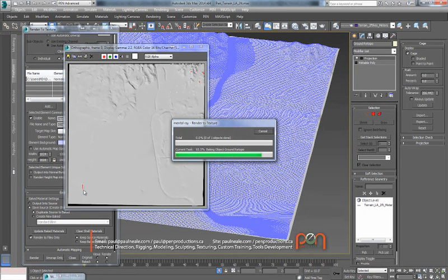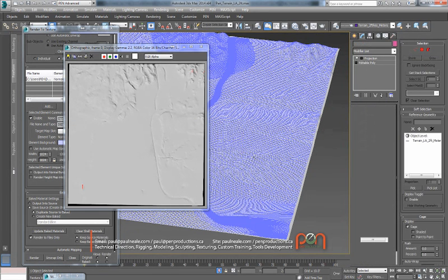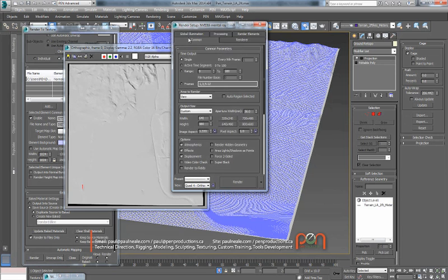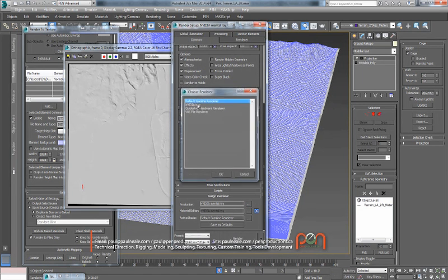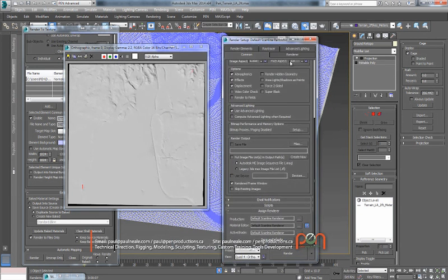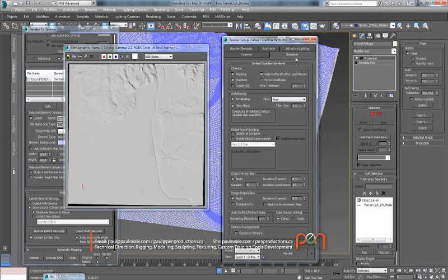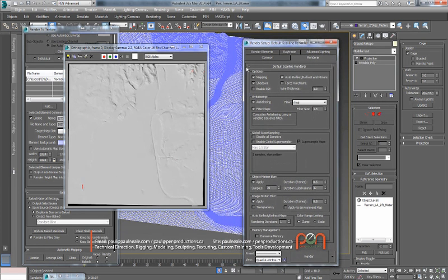Now the other thing is right now we're using Mental Ray because I was set up with Mental Ray. I'm just going to hit cancel, and go over to my Common tab in my render settings and change my renderer back to default scanline. It actually does a better job, quite frankly. It's faster as well. Under the renderer setting, we also want to turn on global super sampling once we have something working, because that'll anti-alias it and make it nice. But right now we're getting these errors. I'm going to leave this off until we're ready for it and try this again.